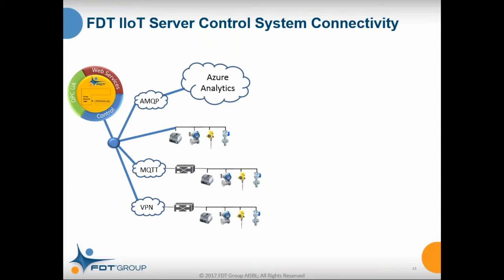And then all of a sudden, when the IIoT conversations and Industry 4.0 conversations started getting serious, people said, hey, this is maybe a viable protocol to move data from one plant to somewhere else. And so there are actually people starting to advertise what are called edge devices that use MQTT. An edge device would essentially be a specialized router that takes whatever protocol is running on the industrial control side, converts the communications to MQTT for the remote site.